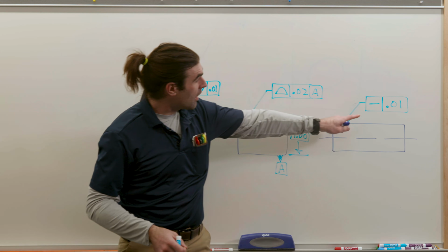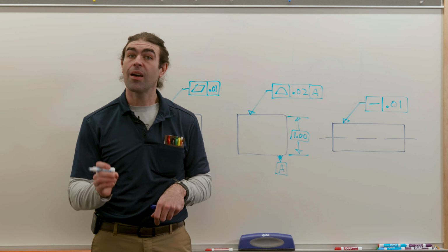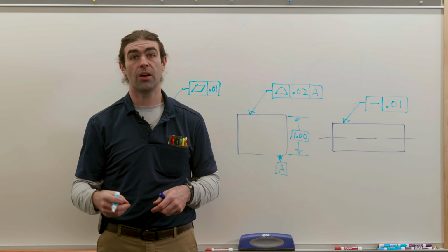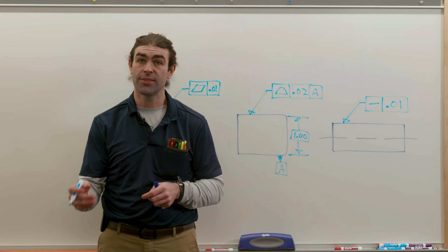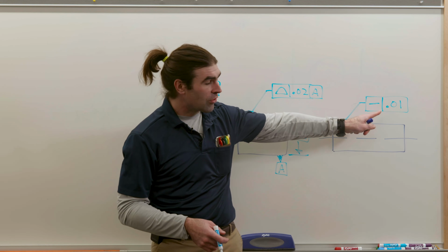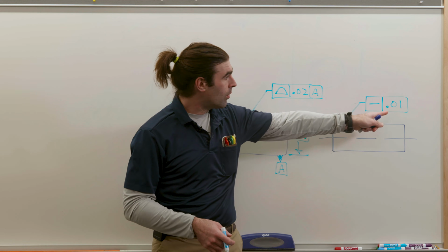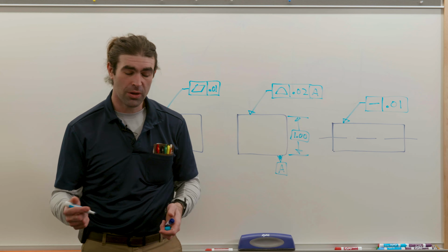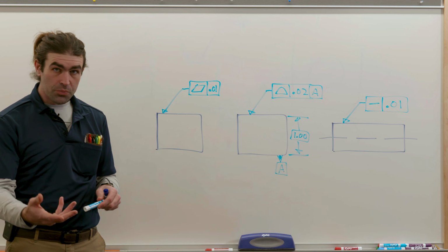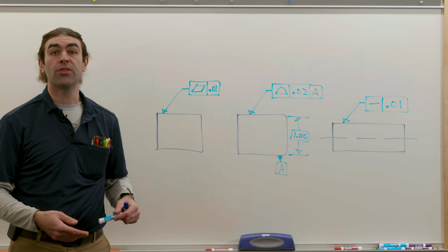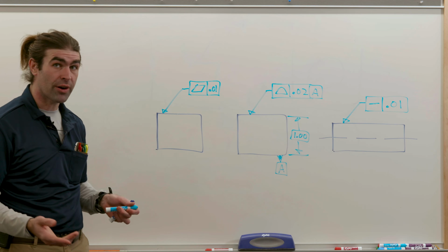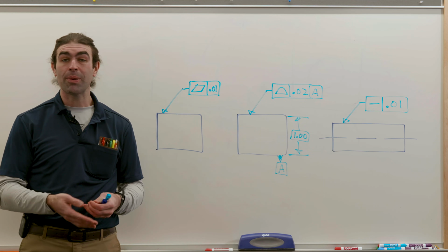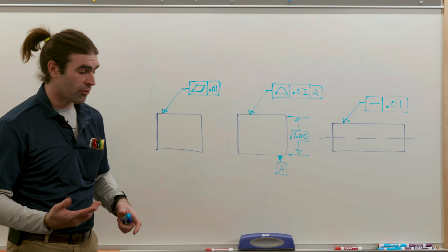And then another form tolerance, straightness, applied to the surface of a cylinder. This controls the line elements around the cylinder. Very simple feature control frame, just a symbol and then a tolerance. Okay? So let's talk about something a little bit more complicated. We'll get into position, which generally has the most complicated feature control frames. So allow us to talk about all of the elements of the feature control frame.